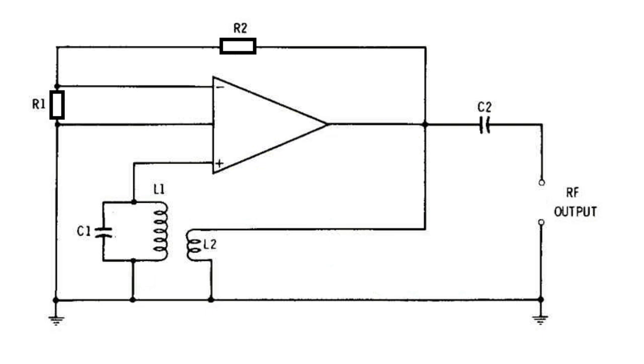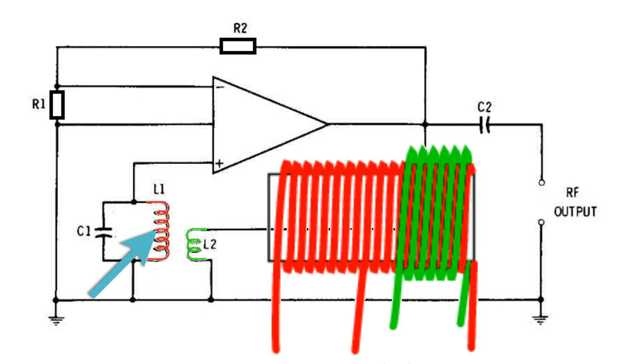In this op-amp oscillator circuit setup, the non-inverting input of the op-amp gets the positive feedback by means of the inductors L1-L2 together. L1 can be the winding of a transformer that consists of a higher number of turns, while L2 can have approximately 1/4 of the turns in L1.